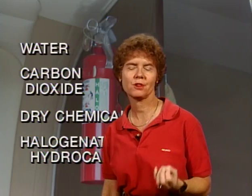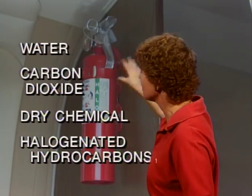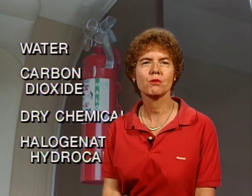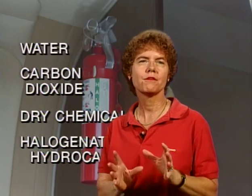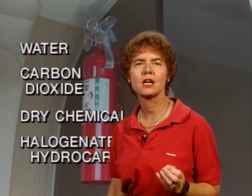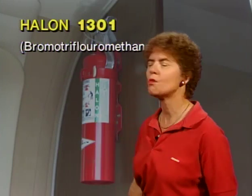Now, the problem with some of these is that if you're in the interior of an aircraft, there may be people in there, and you don't want to suffocate the people in the process of putting the fire out. So you want to use the least toxic fire extinguishing agent that you can. And the fire extinguishing agent that is considered to be the least toxic is halon 1301.